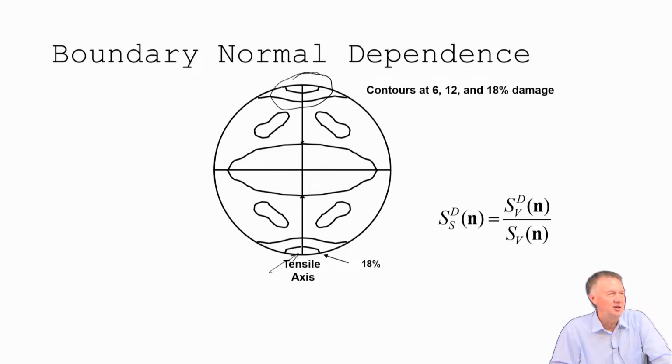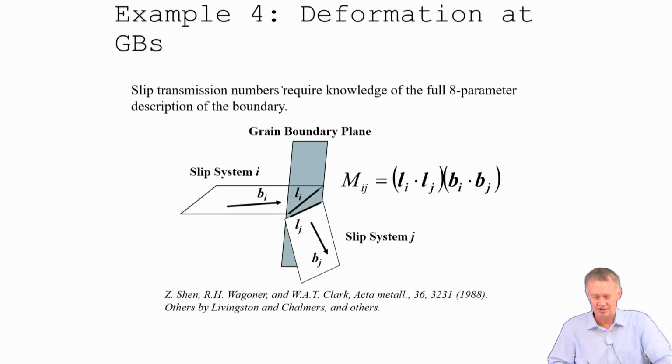I was like, those are coherent twin boundaries, and I don't see any damage on my coherent twin boundaries, right? So then you go back to what's the plane, in crystallographic space, of the boundaries that are damaged? And it was all in the incoherent planes, right? So the sigma 3 twin, the coherent one, was not being damaged. The incoherent one was the one that was breaking first out of all the grain boundaries, right? So that one has a better story that I just skipped.